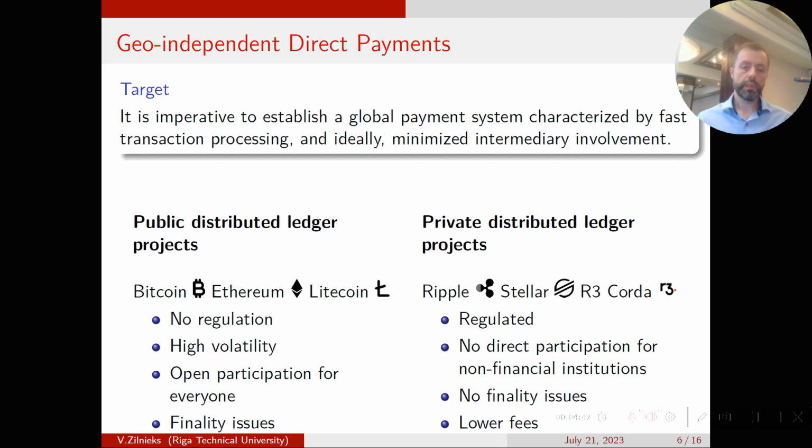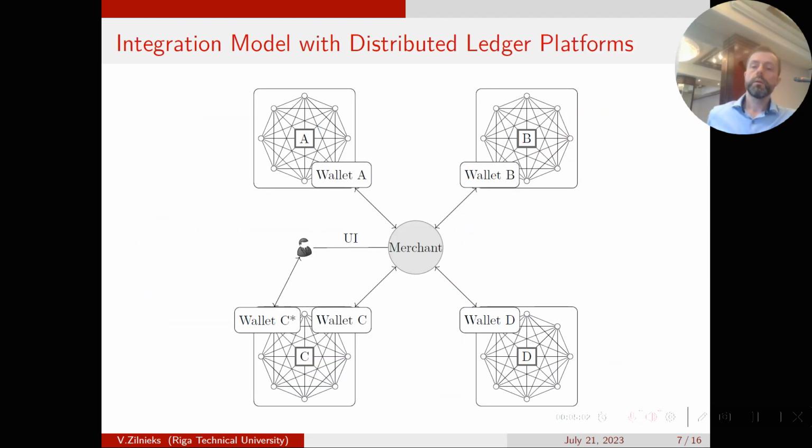We can take the lower water outlet temperature of the electric heat pump. It will change, but for now it is so. The shape of the parabola was determined by imposing that it passes through 3 points. The first one is chosen corresponding to T off, when the plant is off. The second one was chosen in order to satisfy the stationary condition at the most common external temperature.